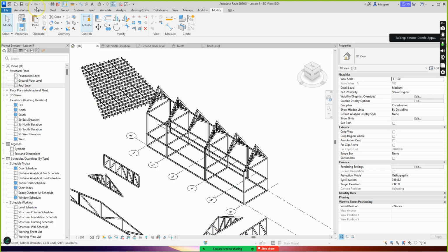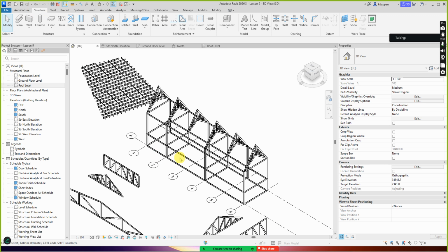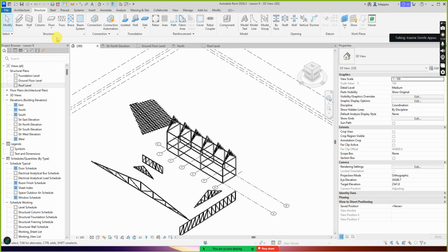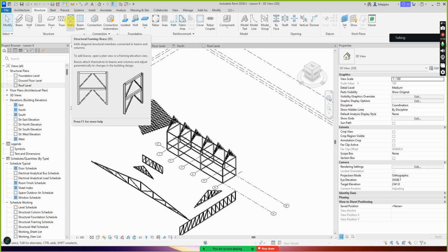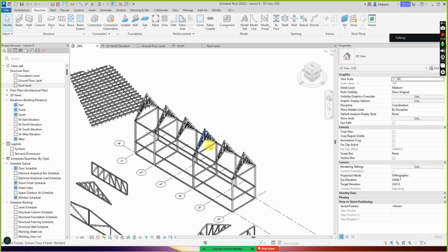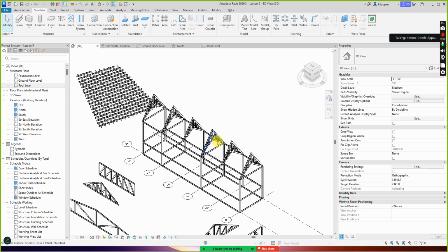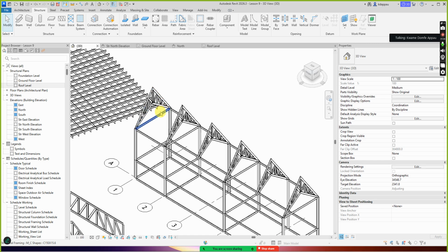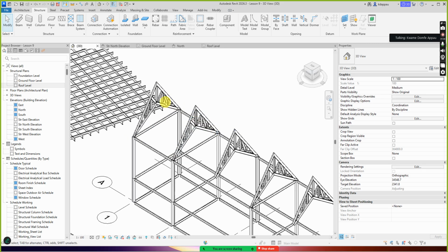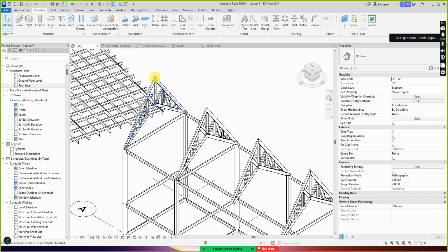The next item I want to look at is a brace. Normally, when you put trusses on top of a building like this one, at times it will be very necessary for you to what? Brace them. So we add a diagonal brace maybe from here to there, and then from the bottom here to the top here, just to brace them.